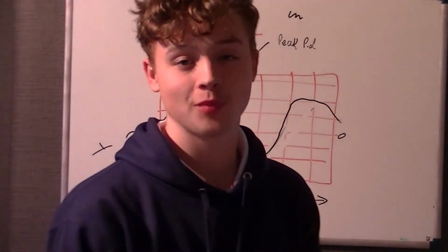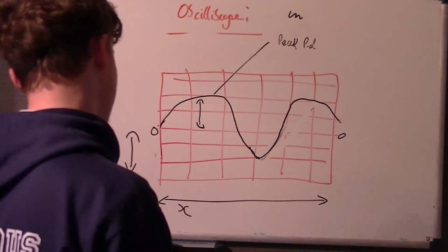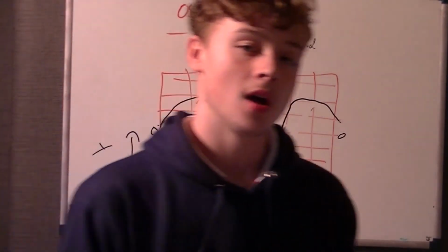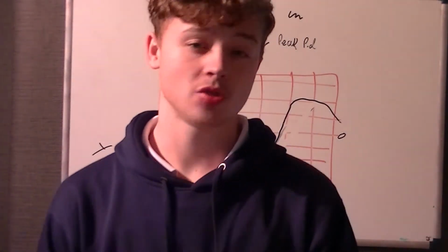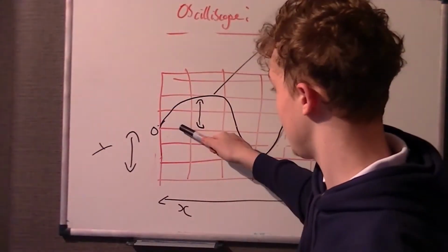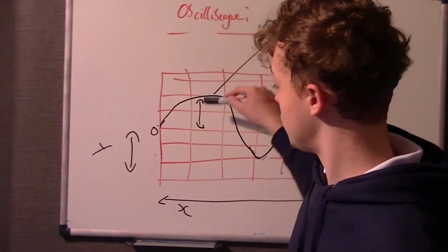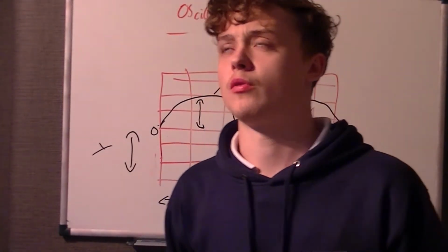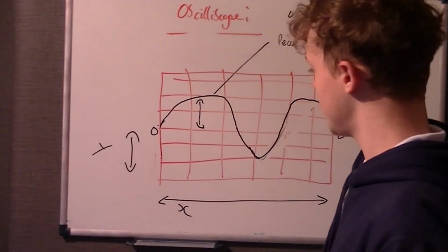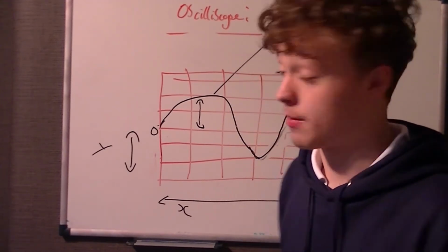So you've got something called the Y gain, and that's basically saying for every centimetre square, what is the potential difference going up? So each square could represent, I don't know, 2 volts per centimetre. So if each square is 1 centimetre, then it's 2 volts. I've tried to make it perfectly 2.